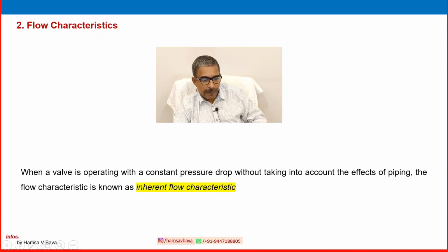When a valve is operating with a constant pressure drop without taking into account the effect of piping, the flow characteristic is known as inherent flow characteristic. So this is the one piece of information to note.